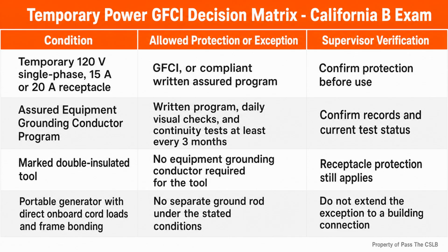The general building supervision question is practical. Before production starts, who has verified the temporary power source, the receptacle protection, the cord condition, and the inspection program if that alternative is being used? A job site habit is not the same thing as a compliant safety system.